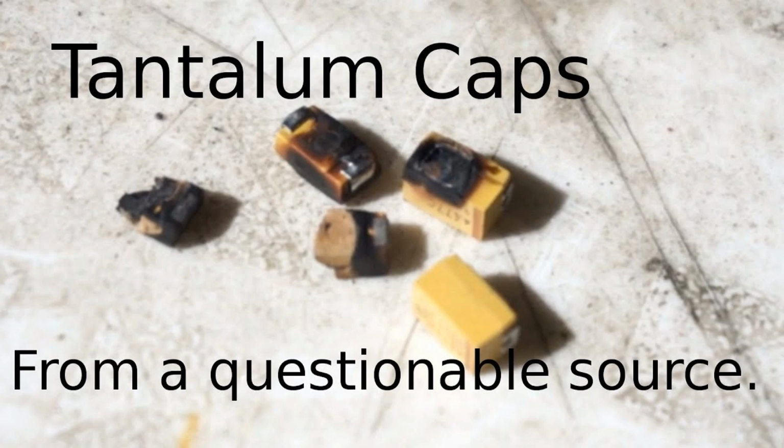Function summary. Energy storage. Tantalum capacitors store electrical energy in the electric field created across the tantalum pentoxide dielectric. Discharge. They release energy when the circuit needs current, smoothing out power supply variations or providing energy for quick bursts of power. High stability. They offer stable performance with minimal change over time or with temperature fluctuations, making them reliable in sensitive or high-performance applications.